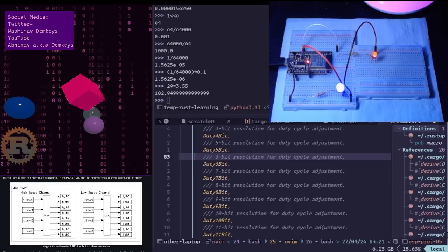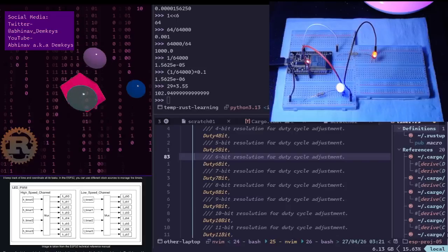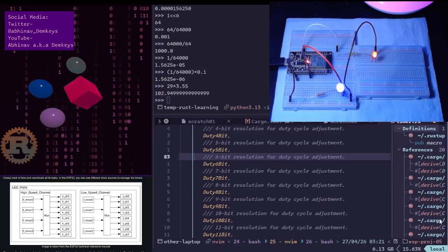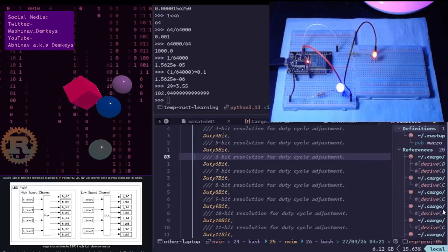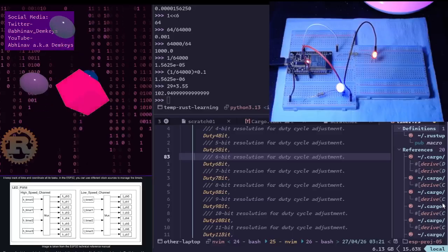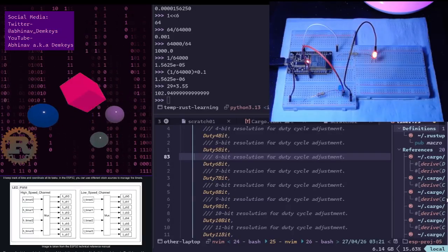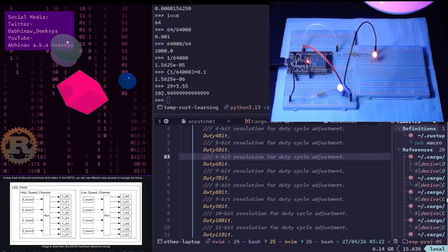What was I saying? Yeah, so these are two different architectures. These are two different chips. They have different tool chains, and they also have slightly different APIs. Fortunately, both the ESP side and the CH32 side build upon embedded HAL, so to a certain extent, the API is consistent.